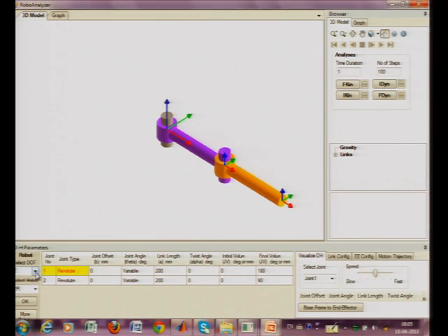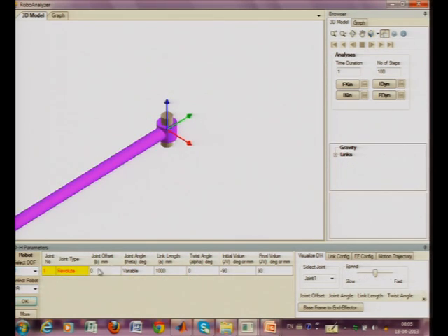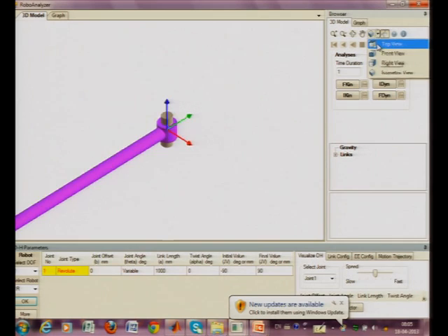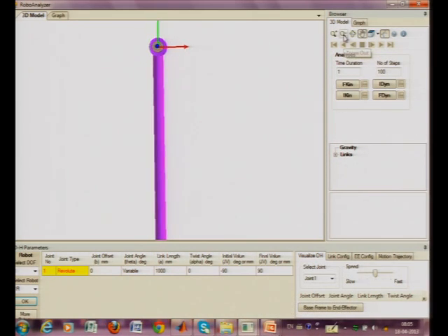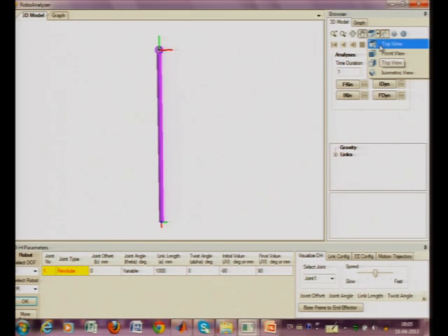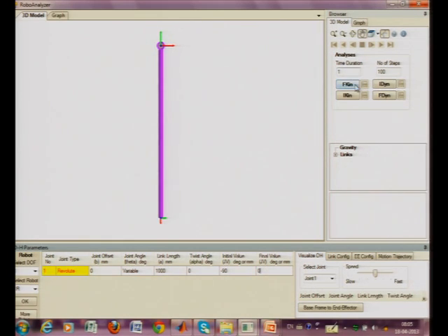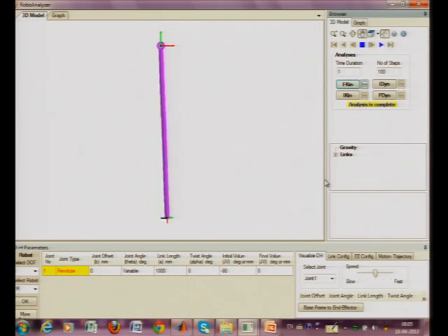So, I wanted to do one link. So, I choose degree of freedom as 1. So, 1 R is here. Then I take the front view of it so that it comes into view. Now this is one link, and at this configuration, if you want to move, here it is moving from minus 90 to 90 degrees. So, I make it minus 90 to 90 degrees, and I perform forward kinematics to see its motion.